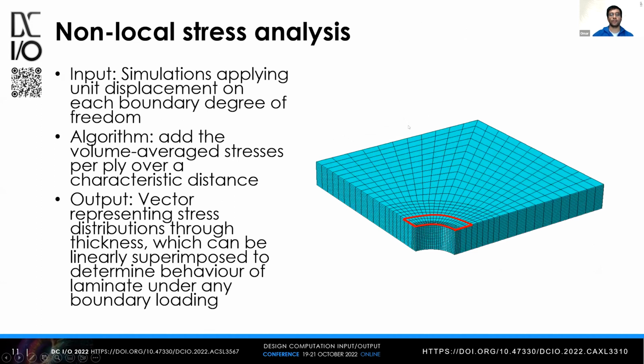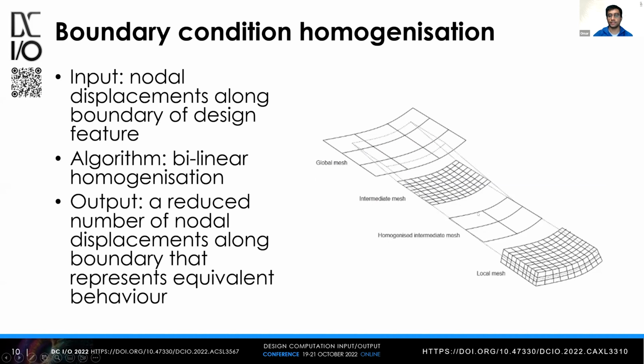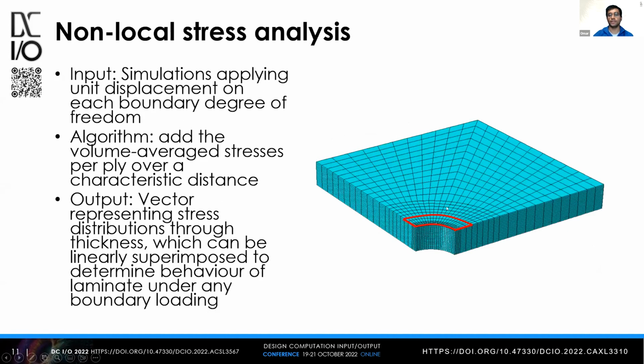Then we use the concept of non-local stress analysis. What we do is we load the intermediate model, as you can see here, with a unit displacement in each direction, and then we observe the stress response in the high fidelity 3-dimensional model.